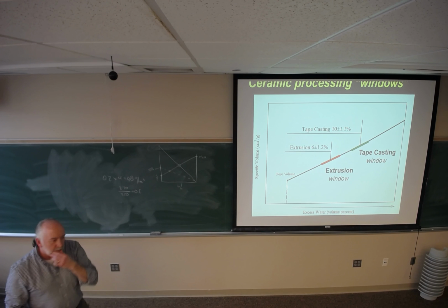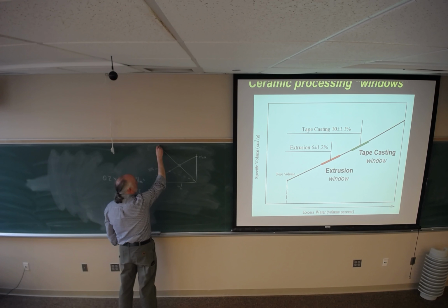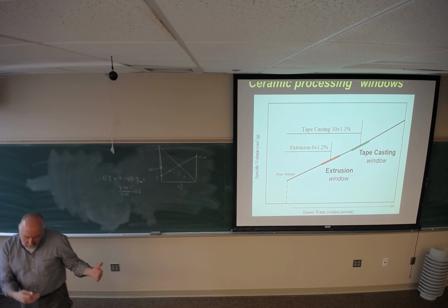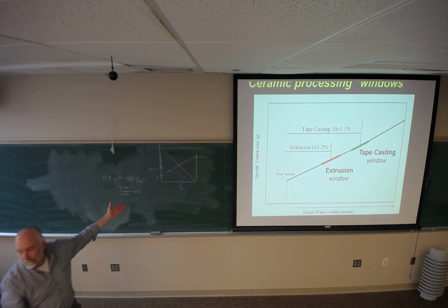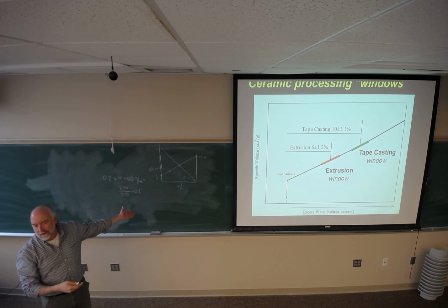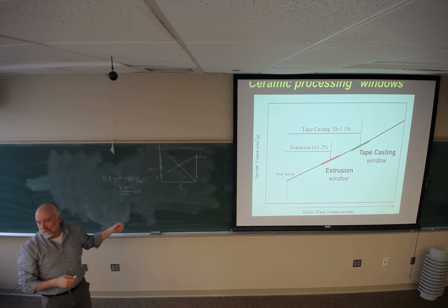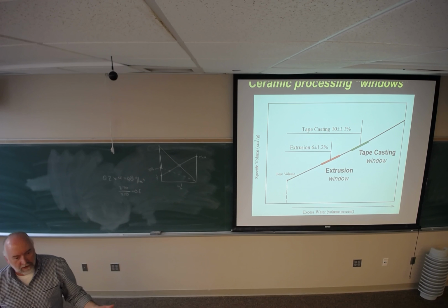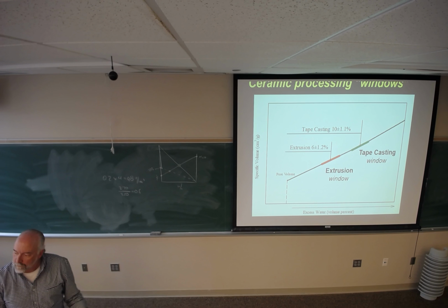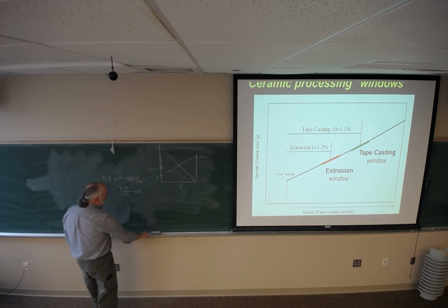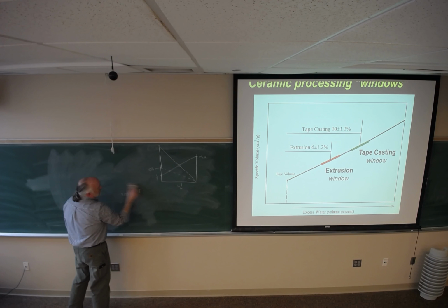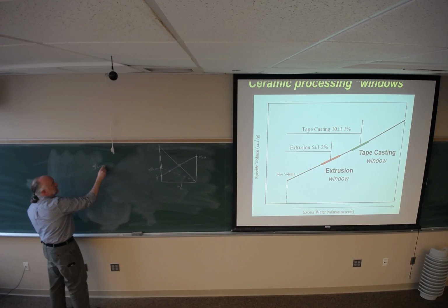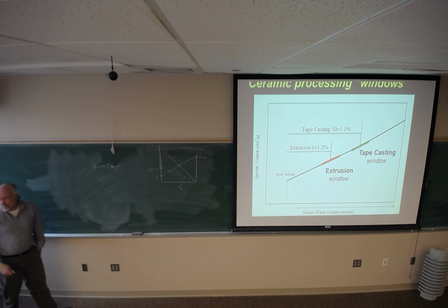When you add water, what happens is that this comes down like this, okay, to that point. If I look at the packing efficiency of my powder and I get 50%, that's because I'm in water. I cannot measure the packing efficiency of that material dry, all right? Because it's not the right packing efficiency. As soon as I put in water, my packing efficiency changes dramatically. And you are going to do forming processes in water. So, we have a slick way of doing this. And we get our packing efficiency by slip casting. Okay? So you would make up a suspension, right?